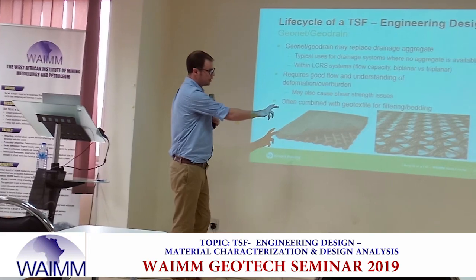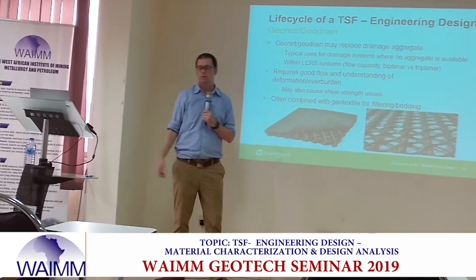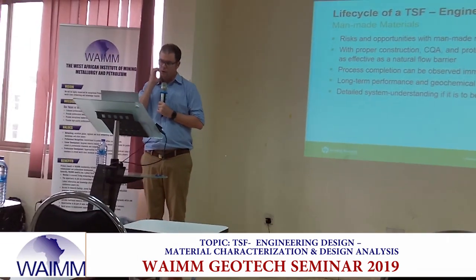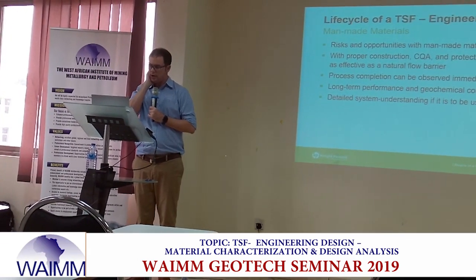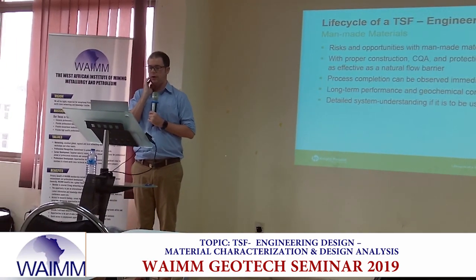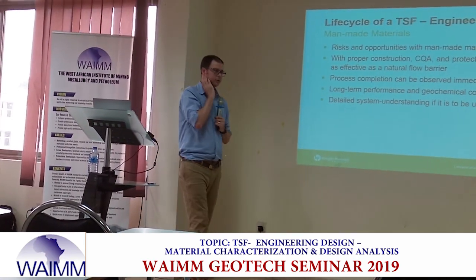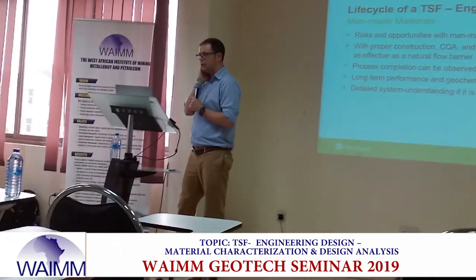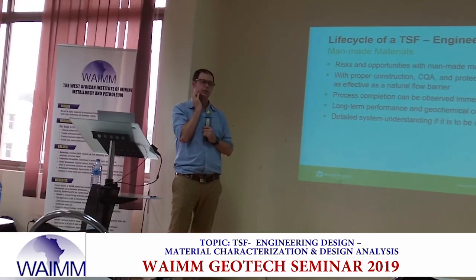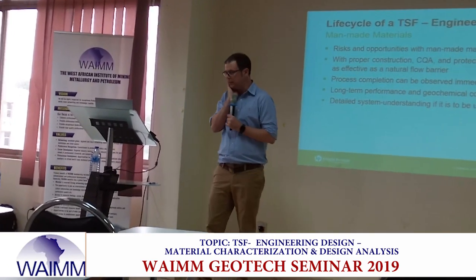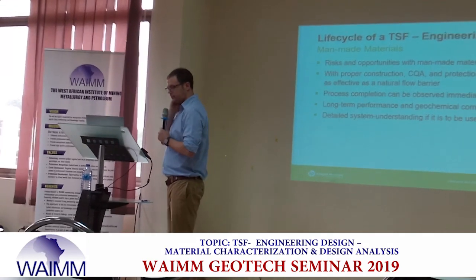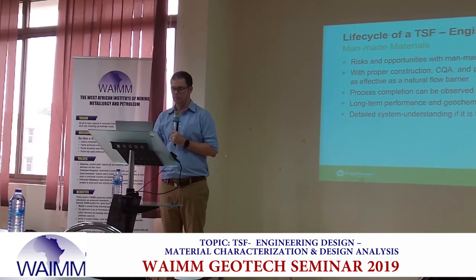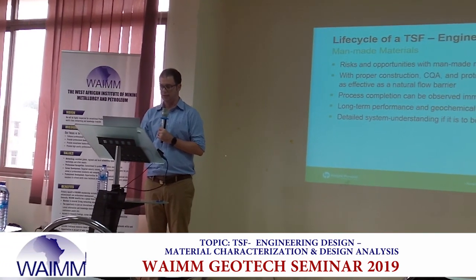For instance, nuclear facilities will require secondary confinement and flushing. Again, with man-made materials, risks and opportunities are always present. And you have to look at quality, you have to look at where you're supplying these from. You have to look at every single roll. You have to do quality assurance during installation on every piece that goes down, as well as all of the welding. You need to have proper construction, CQA, and long-term performance compliance to understand.